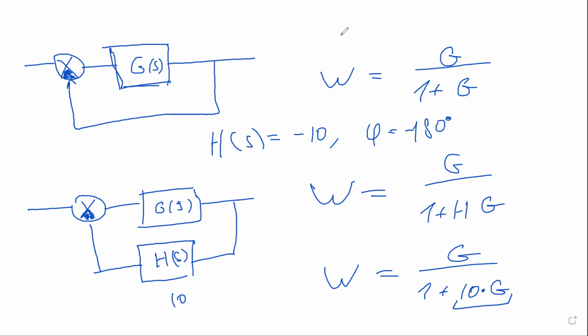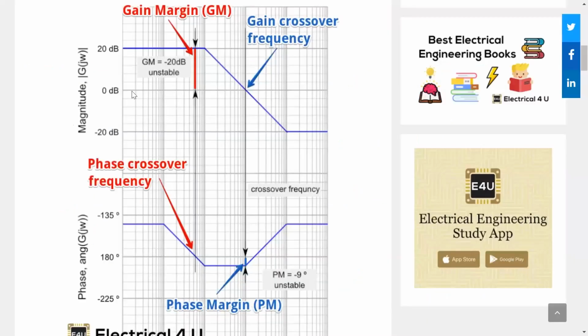And stability margins, let me just go back. So we can look one more time on our thing here. Those stability margins tell us how much we can allow the controller to change. So here what we say is, as long as the controller doesn't shift us by more than -20 decibels, we're okay. If it shifts us by +20, +40, no problem. -10, no problem. -20, big problems.